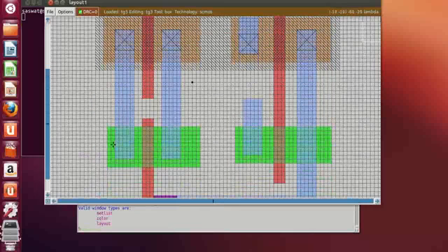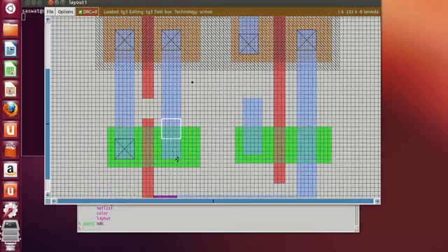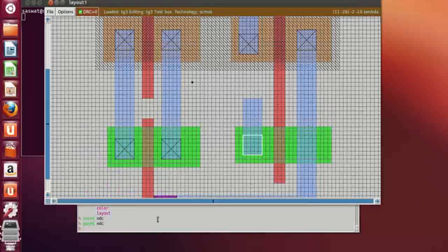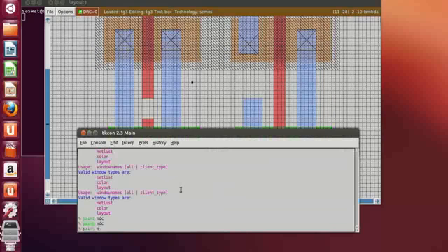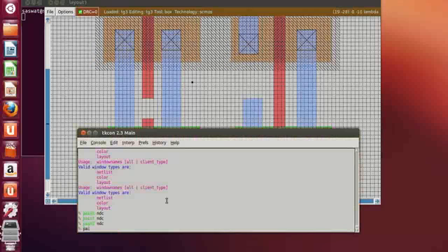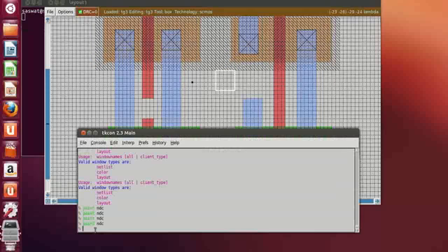Okay. Now over here, the N diffusion contact. Select the area and type NDC, N diffusion contact. Similarly over here also, paint NDC. Now if you want to save this layout at this level, then type save and TG3. So it has been saved now.